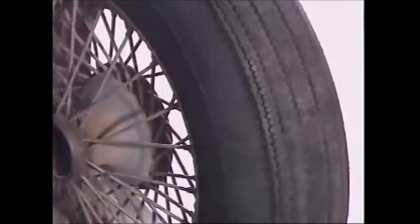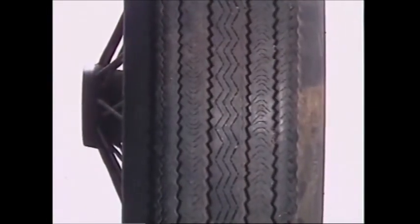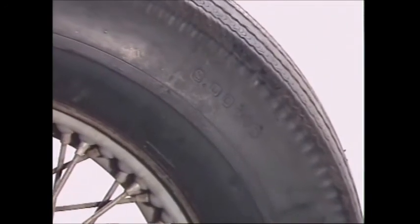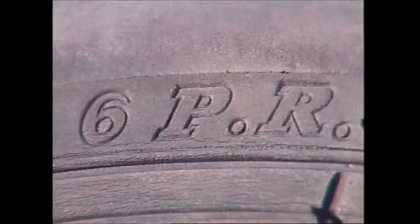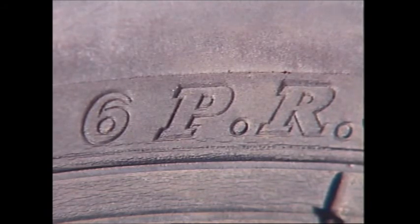In cross-ply tyres, the bead diameter and the section width are stated in inches. For example, 600 by 16 indicates a tyre with a section width of 6 inches and a bead diameter suitable for fitting to a rim which is 16 inches in diameter across the bead seats. The load capacity is indicated by the ply rating, for example 6 PR.